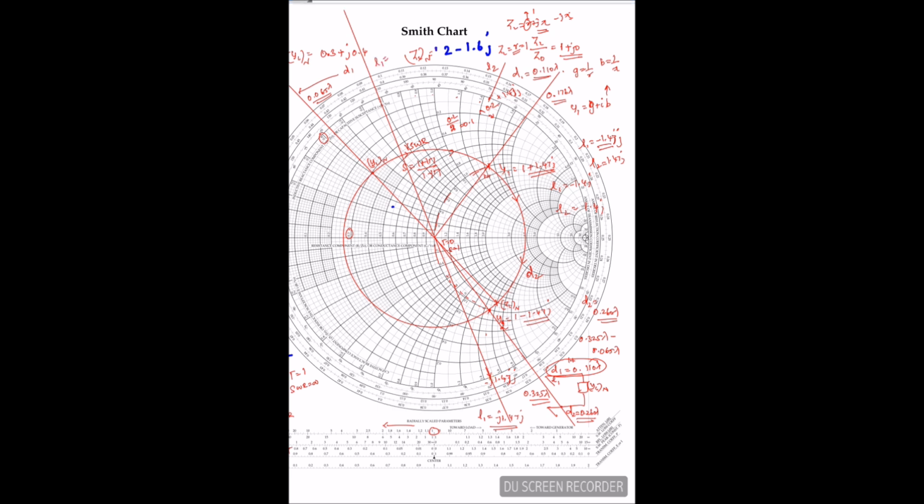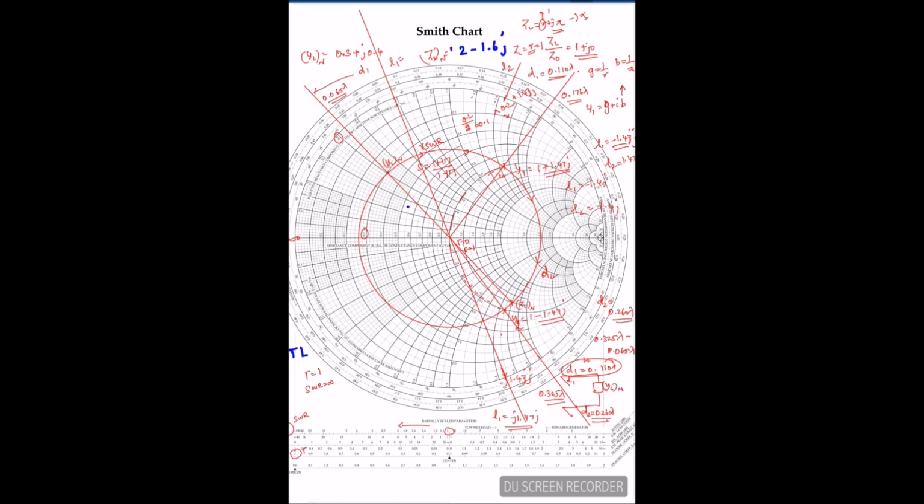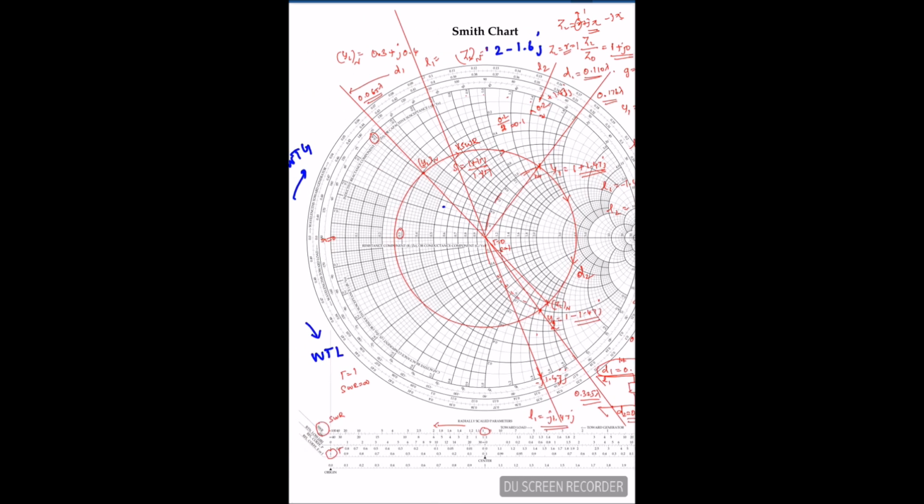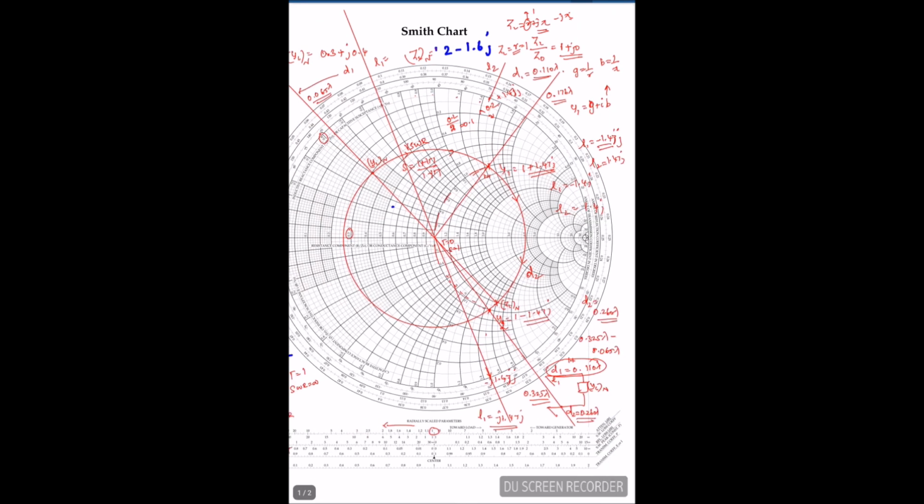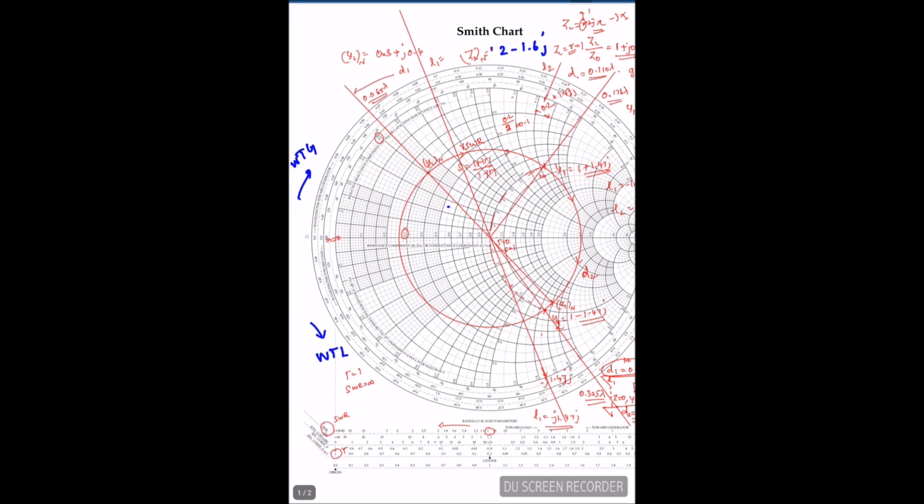in the susceptance domain, that is nothing but shunt admittance domain, I mark this the wavelength. So since it is a shunt admittance, this is a shunt, again the stub is also shorted. The always shorted stub will have 0 impedance and infinity admittance. In the Smith chart, always R equal to 0, X equal to 0 and Z equal to 0. Impedance is 0, meaning that admittance equals infinity.